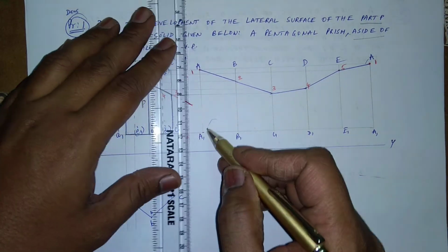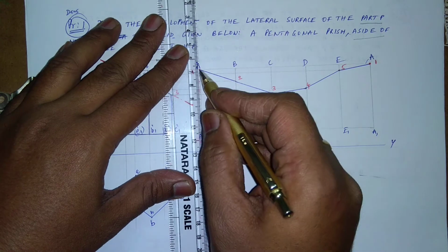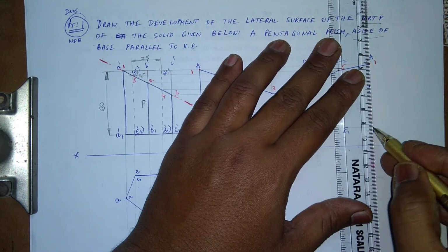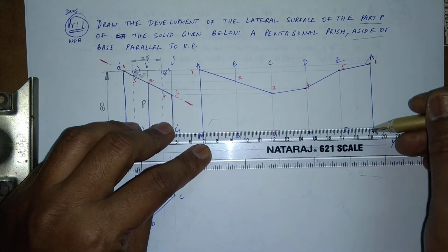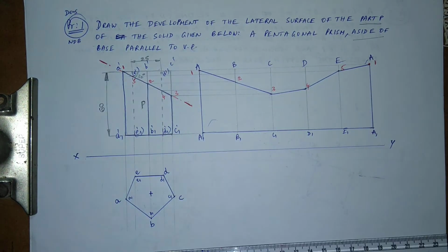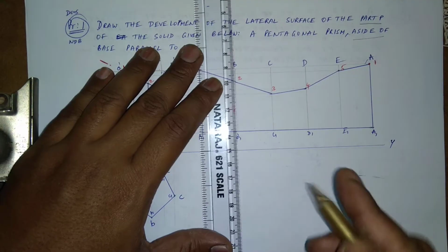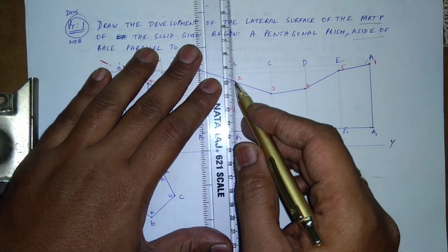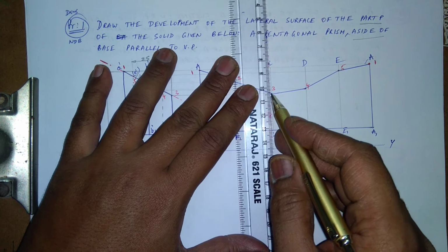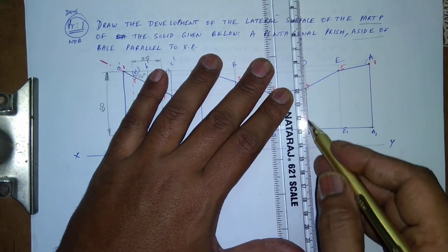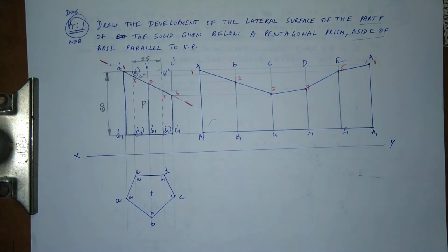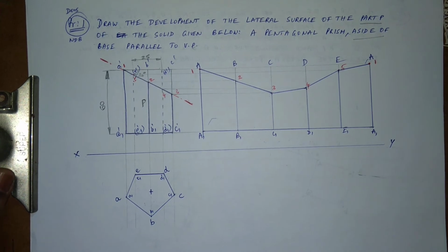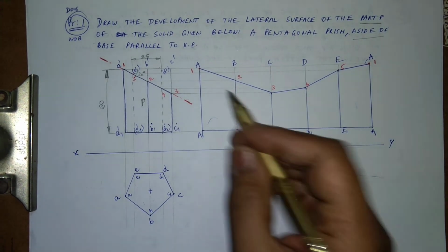So this is the bottom part which has been developed, and the top part has been removed, right? As you know, the top part has been removed, so the bottom part is the one which is remaining. So this one is darkened with an HB pencil. And of course these are also solid lines, because you see these edges, right? The edges are there. This is also solid lines. So you could have drawn this with an H pencil. All this initial construction was in H pencil, and then now the development, whatever has been developed.